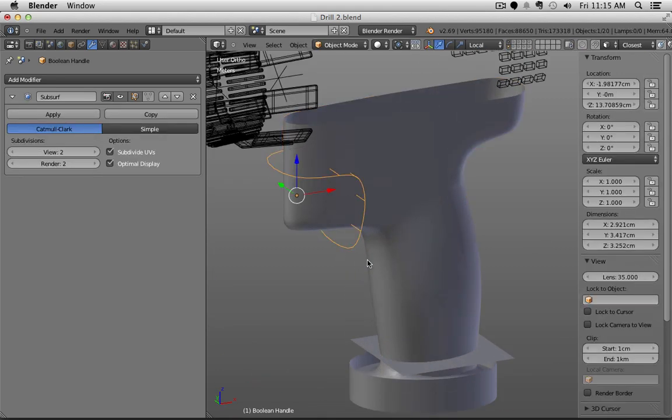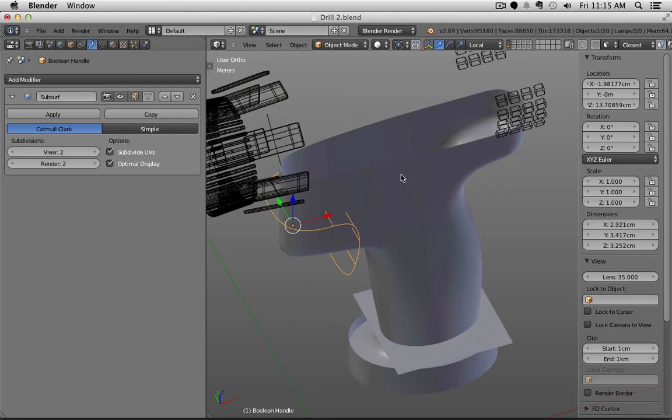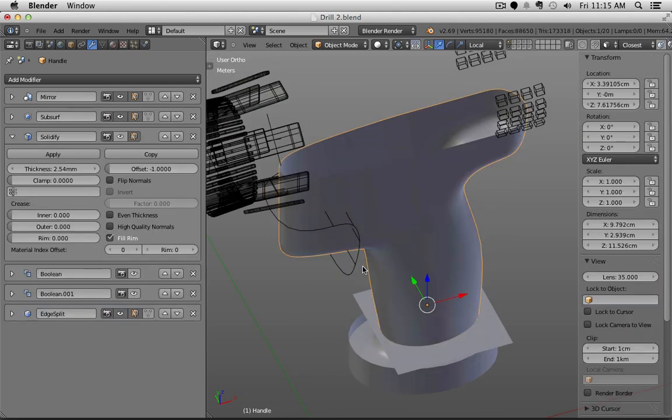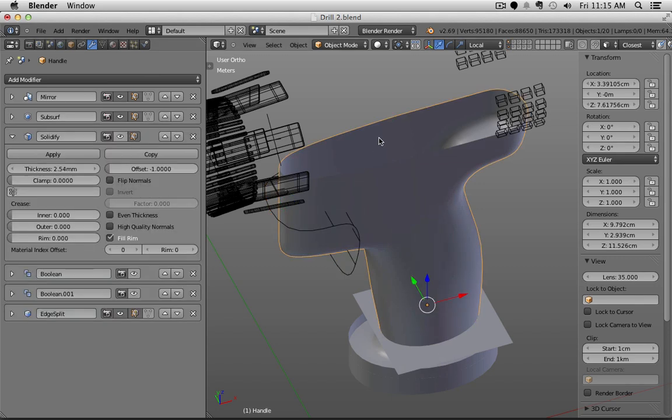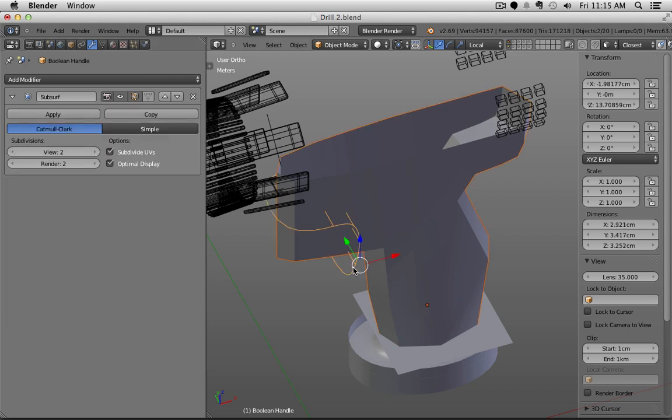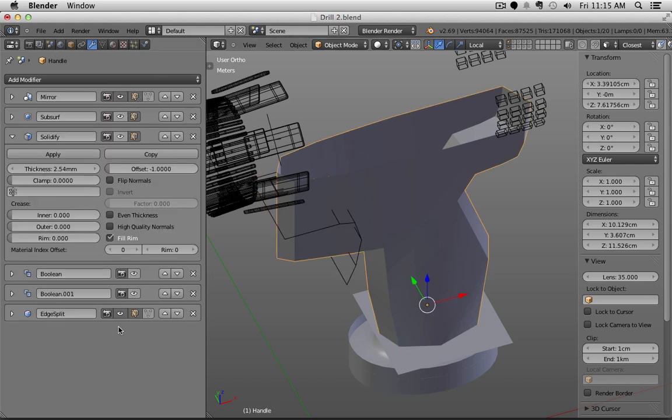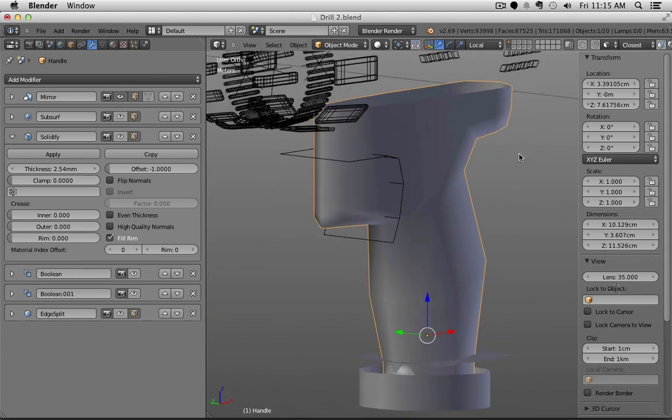So this surface here, which for example cuts out the front part, and the mesh for the handle, those two I would like to transfer over into Fusion. This object is using a mirror modifier, so I can, for example, turn those functions off, so I have everything turned off besides just the mirror modifier, because I would like to bring over a complete handle.